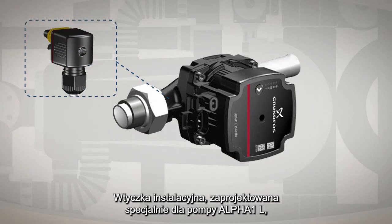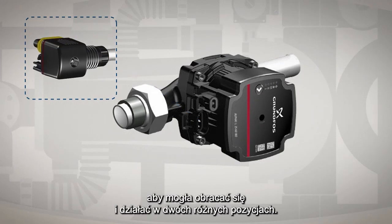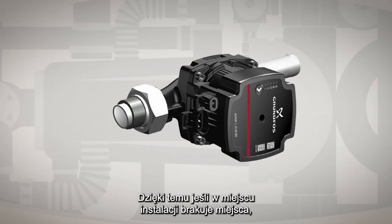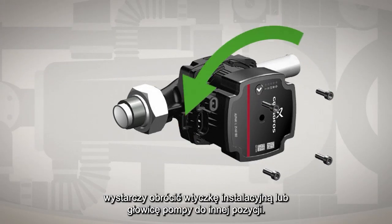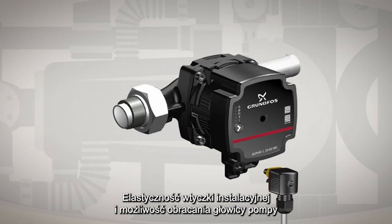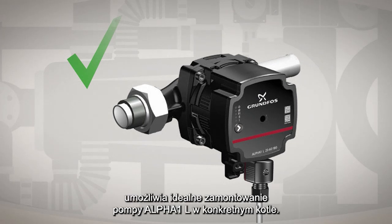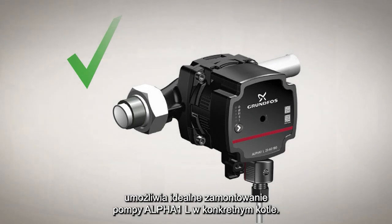The installer plug, designed specifically for Alpha 1L, is devised in such a way that it can be rotated and function in 2 different positions. That way, if space is lacking in one area of the installation, simply rotate the installer plug or the pump head to the other position. The flexibility of the installer plug and the ability to rotate the pump head allows you to install the Alpha 1L perfectly according to your boiler.